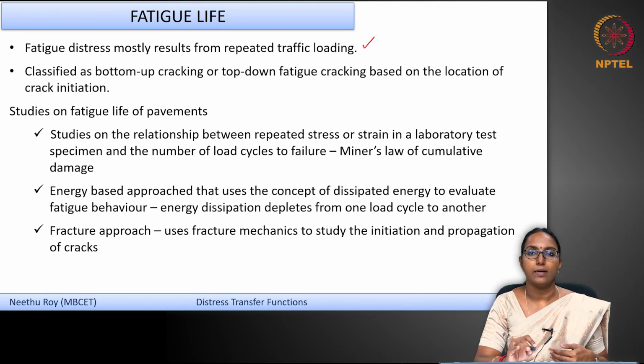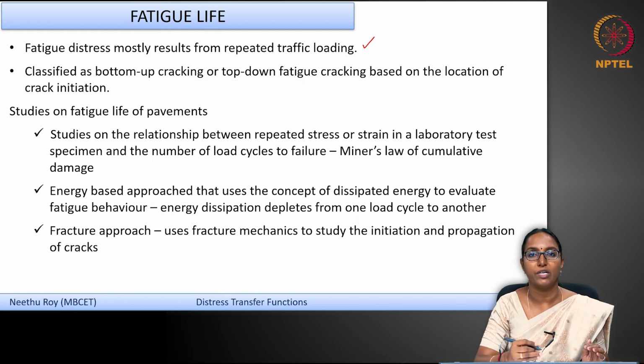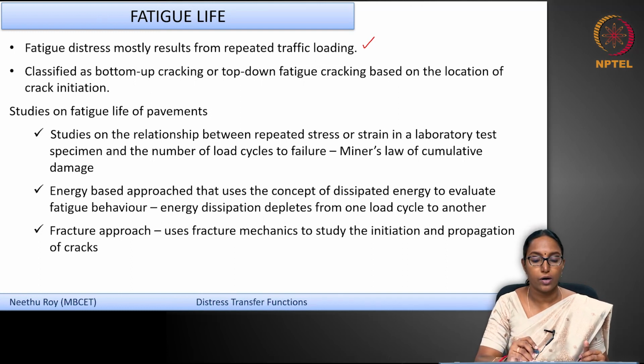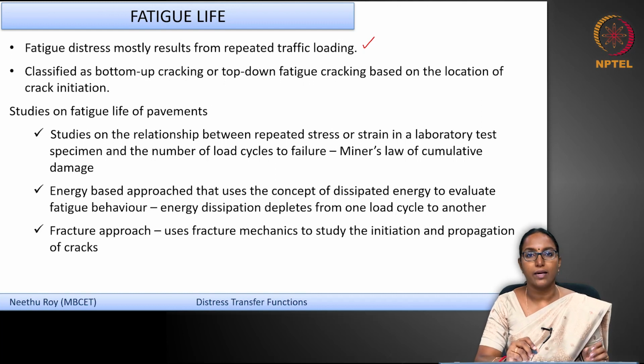So, all other layers, the granular layer or the subgrade layer, we are not considering the fatigue resistance of these materials because they have very negligible fatigue resistance as compared to the top bituminous layer, okay. So, in order to study this fatigue behavior or the fatigue characteristics or the fatigue life of a bituminous pavement, essentially you can have three approaches.